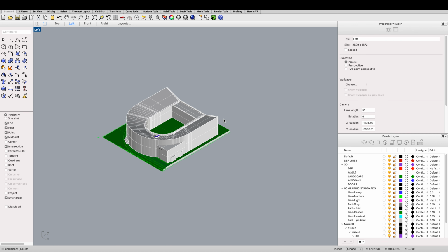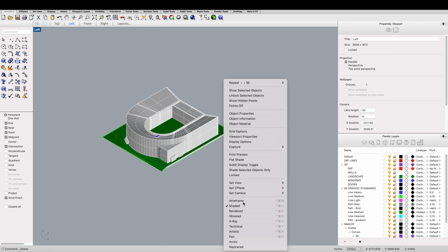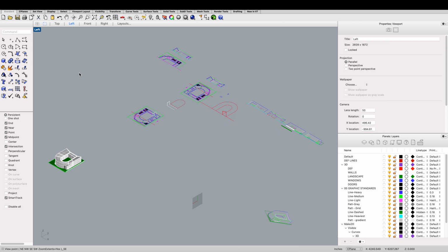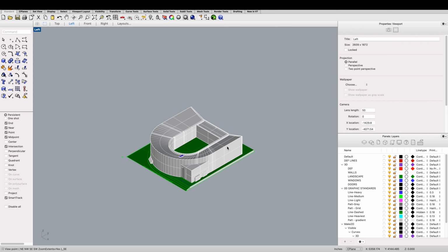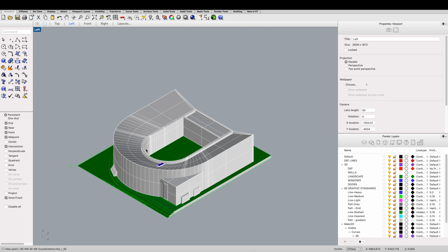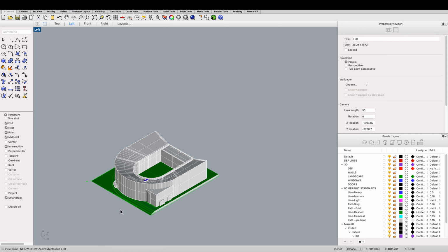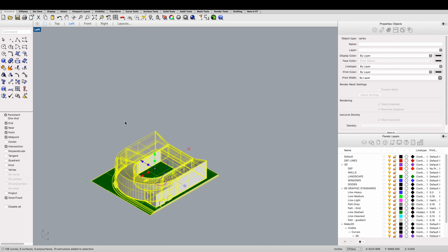But so to get to the perspective we want, you want the U to be right side up, and then you go to set view, and we're going to be doing isometric southeast. And then everything will be isometric. So here's the view we're doing of our house. You will see right here is where you put the door in. Here's where you'll see the opening. And this is where you will make 2D. I would make sure you turn off your graphic standards, because sometimes you can carry lines into your make 2D that you don't want.